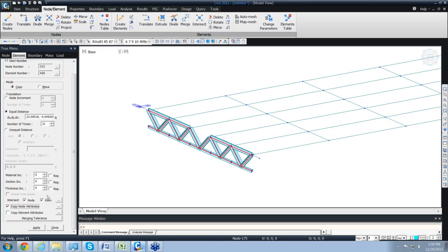So I do have one more question. Sure. When you put the girders in, the node points and the lines for the girders, where are those actually located? Is that the top of the girder? It's generally at the centroid of the cross section, which is just below the top flange. Okay, so but you can, section? Yes, but you can move it. I mean, if you want to move it to some other location, you can do that. But generally, the centroid is the best location.